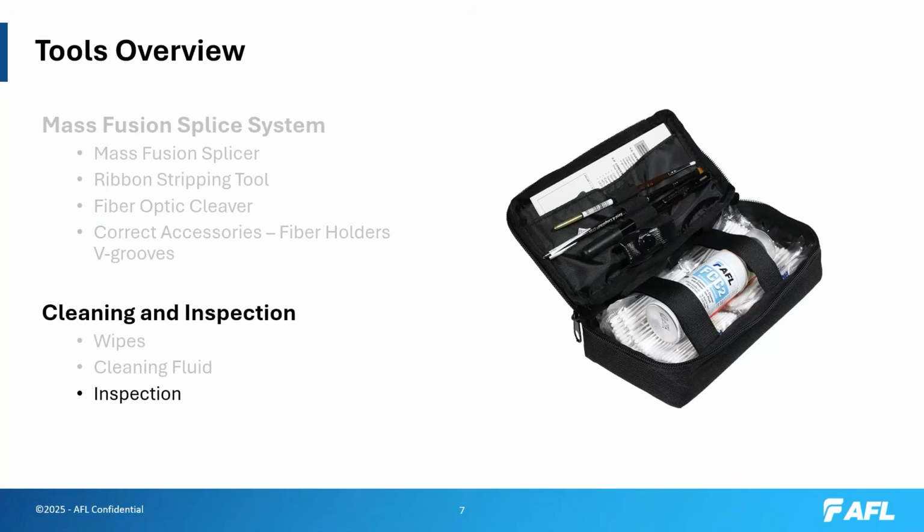The problem with this is they really didn't have the ability to see what we were seeing, because we were using a stereo microscope. We were magnifying that fiber approximately 50 times, and looking at those V-grooves blown up about 30 times with that stereo microscope. So the inspection kit has a little jeweler's loupe and also a little white pin light to allow the operator in the field to magnify and inspect those V-grooves, which is a critical part of that operation.